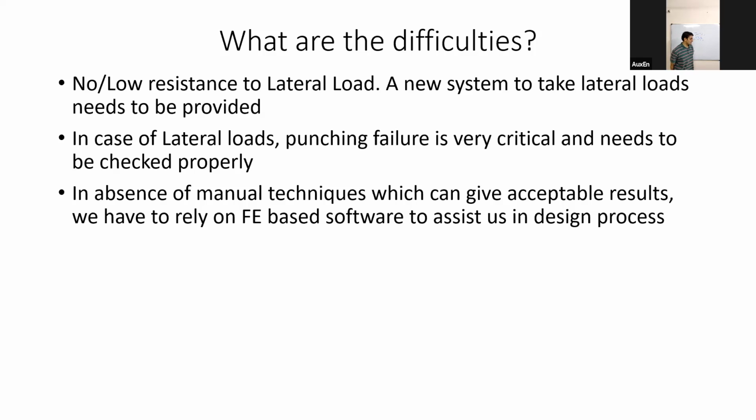As Mr. Razi is rightly saying, when you have a normal slab beam column system, the lateral load flows from the slab, and from the slab it is transferred to your beam, and the beam and column together form what is called frame action, and through that frame action my lateral load is transferred from beam to column.